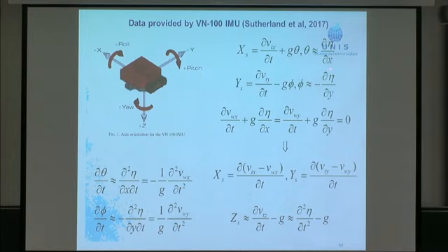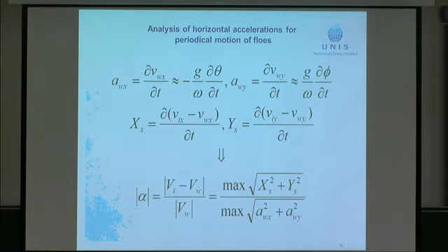So then if we consider acceleration of water particles in water with open surface without ice, this term is just proportional to acceleration of water particles. Therefore, from accelerometer records I have directly these quantities, the difference in accelerations between floe and water. And in addition, of course, I have these angles and angular velocity, which are proportional just to water accelerations. So when I take this quantity from field measurements, I can estimate this coefficient as this ratio.